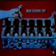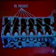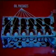The crankshaft will be mounted on insert-type main bearings on these supports and attached with main bearing caps. The term main, incidentally, refers to the parts used in mounting the crankshaft. Each of the main supports contains an oil passage. These passages will align with holes in the main bearings to lubricate the crankshaft as it turns in the bearings. The crankshaft for this engine, then, has 7 main bearing journals to mount on the main supports. A journal is a round bearing surface.